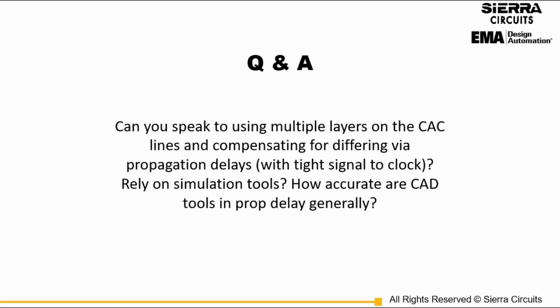Yeah, and on the simulation side, you have options in extraction. This is where the extraction choice would come in. Typically, if the z-axis type delays are of importance to you, then you probably want to extract using a 3D solver.